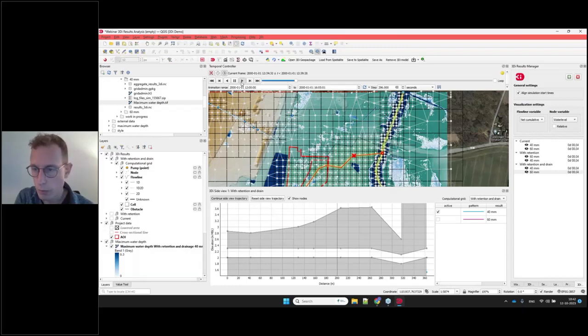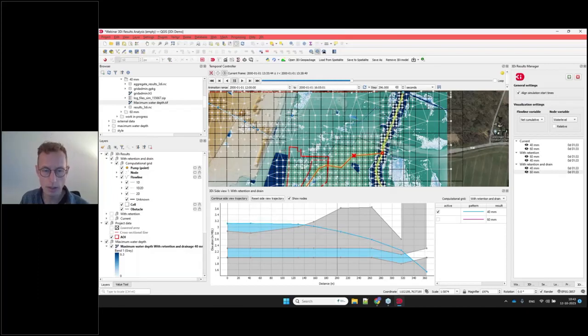Well, at the beginning, the first hour, there's no rain. Here you can see the simulated time. Here you can see the real time. Let's pause it quickly here. So what we see is that even after half an hour of rain, the gradients in this pipe are really strong.